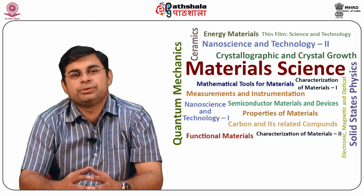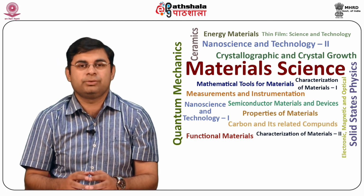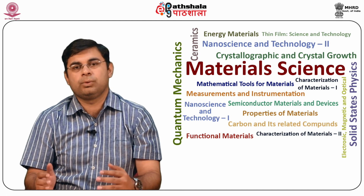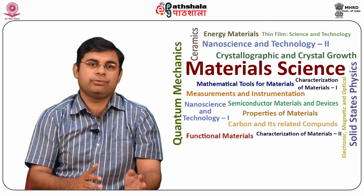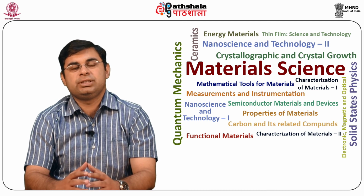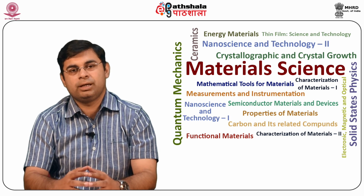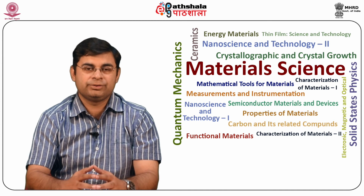Capacitive transducers. A capacitive transducer is a variable capacitor whose capacitance is varied by a non-electrical quantity being measured. The capacitance C for a parallel plate capacitor is given by the following expression: C = epsilon naught into epsilon R into A divided by D farads.